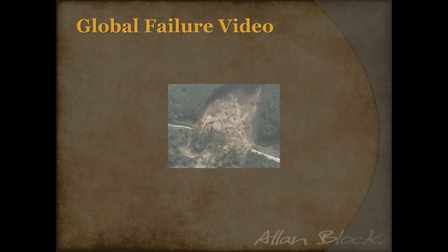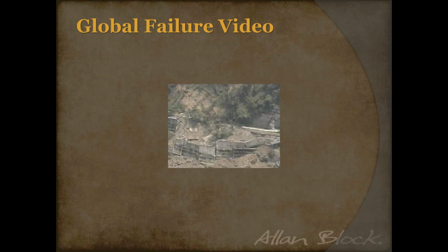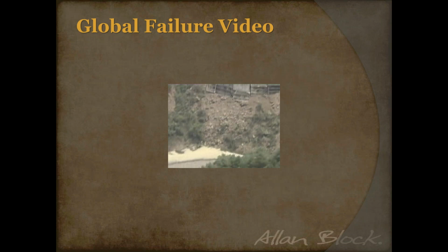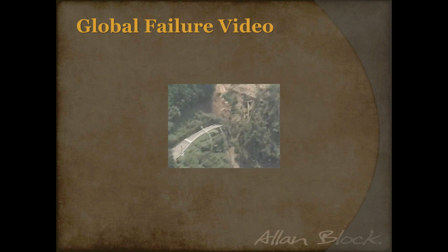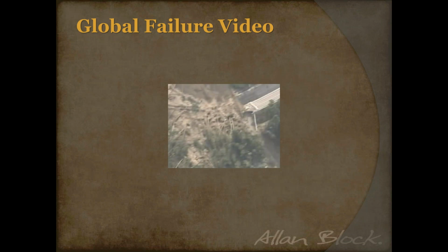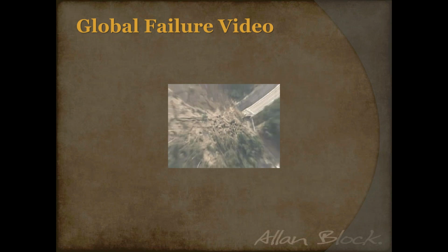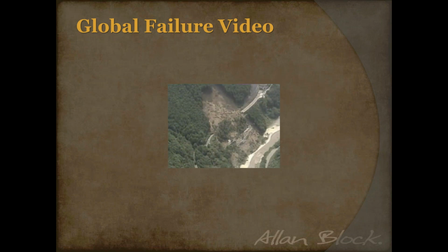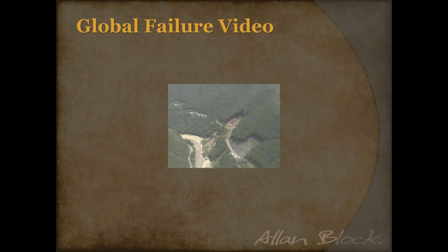As you can see, the full fallout. There were some retaining walls and road structures on there, and no matter how well those were designed, it was the slope that gave way, not those designed structures. You could also notice that when some of those trees were coming down, they were coming down perfectly vertical, how they're supposed to be on the hillside, and they just came down with the slope. So that means it was a deeper failure than just the surface or the wall.